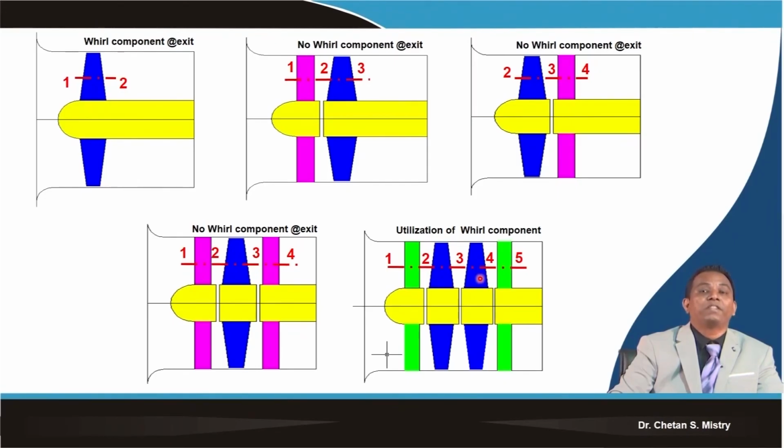We are only interested in cooling, where mass flow rate is the major concern, so you go only with the rotor configuration. When we have a special requirement for axial exit, we have the configurations we have discussed. And contra-rotating gives you a whole lot of benefits, which we will discuss in detail when we go to the design of the contra-rotating fan.